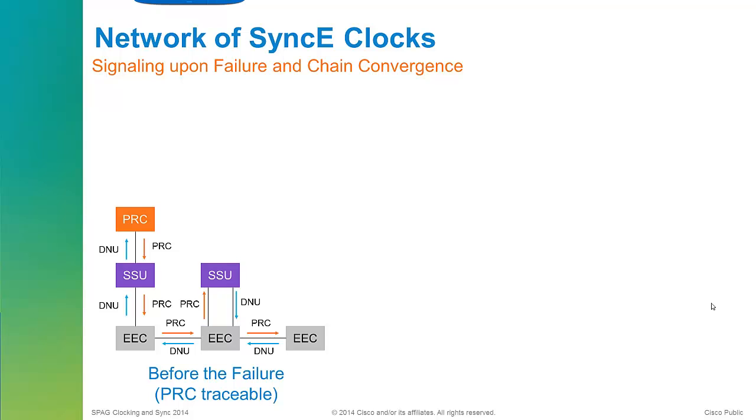The packets that are in Synchronous Ethernet are ESMC packets. And ESMC packets are only used to carry the clock quality information. So it's not actually used to carry the timing information either. ESMC runs in an OSSP protocol, Organization Specific Slow Protocol, which is defined in 802.3, and so it's just a few bits of data that are passed around about clock quality. So just something to remember. Synchronous Ethernet, really there are no packets involved. ESMC, yes, there are packets involved.